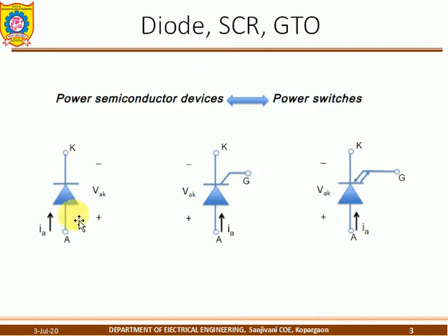The voltage drop across it normally starts at 0.6 V. Depending on the manufacturer, it can drop 1 V or 1.2 V. Like that, a voltage drop takes place in the diode. One more major thing is that it flows in only one direction. Once the current flows, that is why the arrow mark is used in the diode symbol. The diode consists of only 2 terminals.